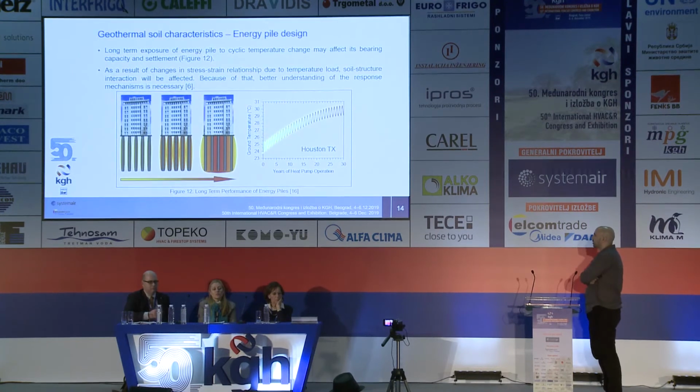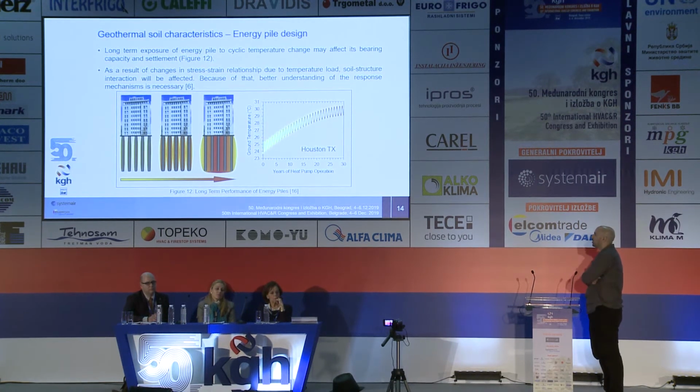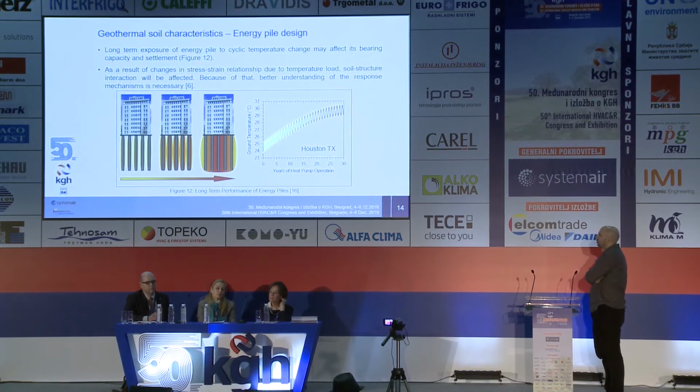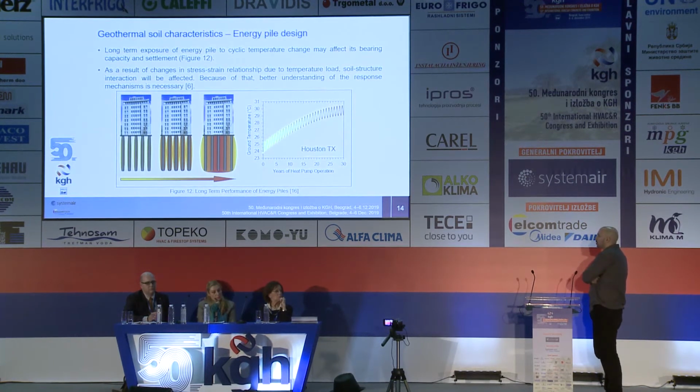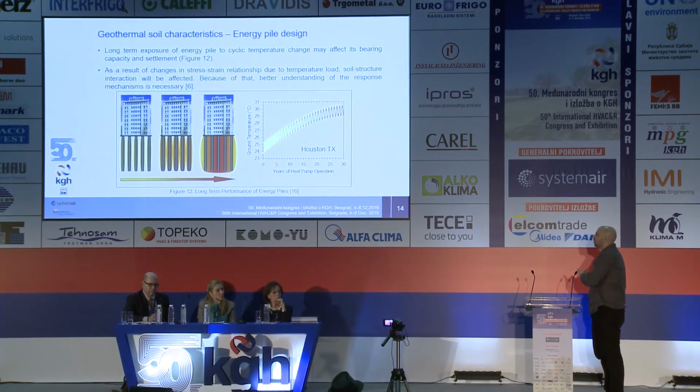Also, we cannot neglect the long-term effect of the exposure of energy pile to cyclic temperature change. It can affect its bearing capacity and settlement. Settlements of the structure are not negligible because they may lead to bigger issues during the long-term exposure, because it can lead to weakening of the capacity of the structure.